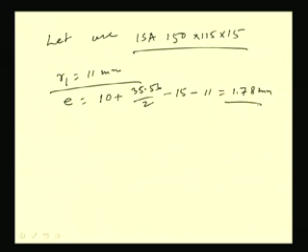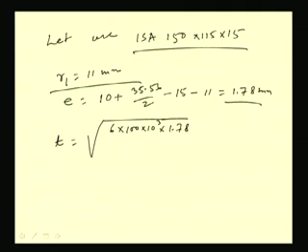So, eccentricity we are getting this much. Now the required thickness again can be found out, T is equal to 6 Re by sigma Bs into B. That means 6 R, R was 100 kilonewton, E is 1.78, B is 150 and sigma Bs is 185.